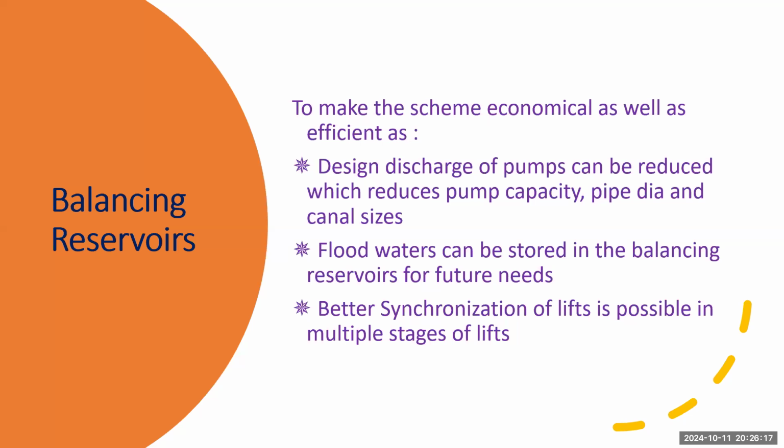First, the design discharge of pumps can be reduced, which reduces the pump capacity, pipe diameter, and canal size. So if there are balancing reservoirs in between, then the design discharge of the pumps can be kept low, which results in reduced pump capacity, pipe diameter, as well as canal size.